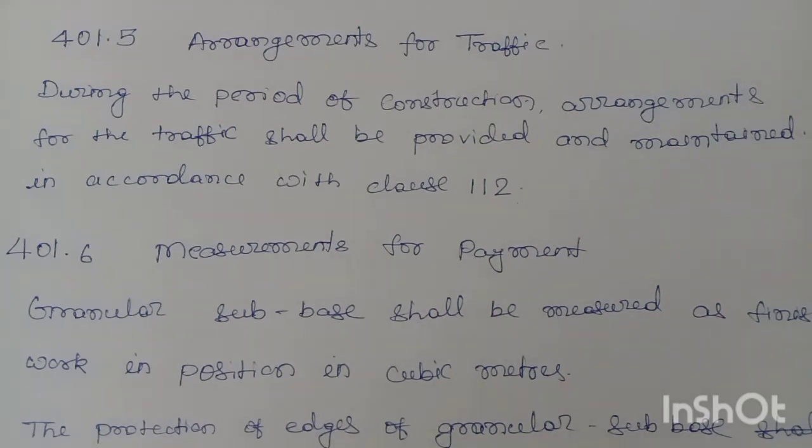401.6 Measurement for payment. Granular sub base shall be measured as finished work in position in cubic meter.